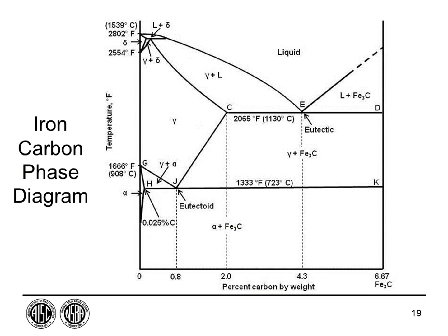Now, we have to talk a little bit about what's happening internally in the steel as we're cooling it down. The steel starts up here at this very high temperature, and we're showing temperature versus percent carbon. This is what is called a phase diagram, and this is just for the elements of iron and carbon. We start out at a temperature way up here, and as we roll the steel, we're rolling it in this solid phase that's called the gamma phase, and then we cool it back down, and into this range is where we're going to be using it.